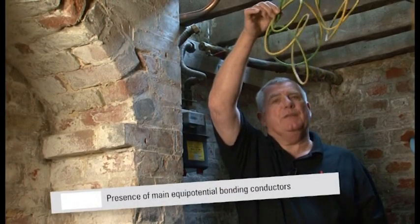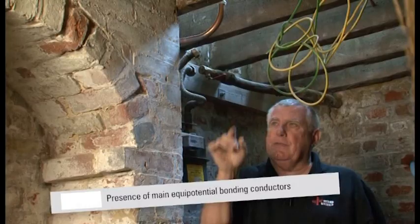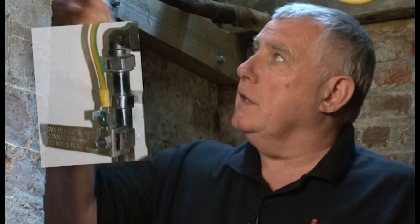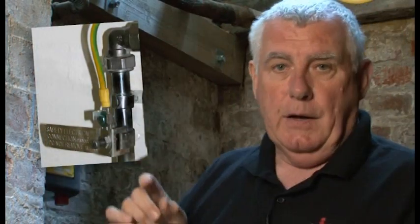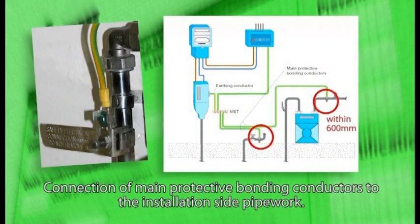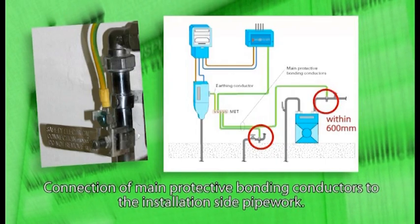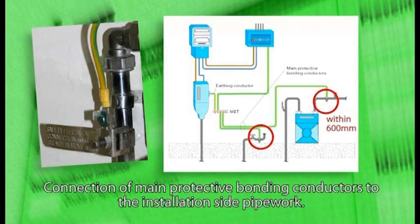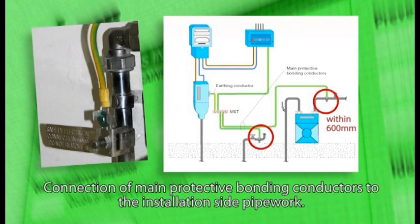Next, we have the presence of protective bonding conductors. These connect from the main earthing terminal to extraneous conductive parts, for example gas or water pipes, which may introduce earth potential into the installation. It is important to check that the connection to any pipework is on the installation side and not on the supply side, and is made as close as possible to where that supply enters the premises. Where practical, this should be made within 600 millimetres of the meter outlet before any branch pipework, or at the point of entry to the building if the meter is external.